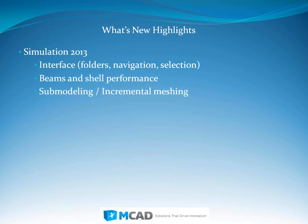What's been introduced, and what will probably be the subject of another webinar in the future for you guys, is submodeling, where we can do what's called incremental meshing. We can mesh individual parts now. We don't have to remesh the whole model if we want to change something about a particular part, about how it's capturing the geometry. We can also run these submodeling studies where we take a larger assembly and break it down into smaller parts and look in detail at some of the more refined areas where we can get extra refinement and dig into it a little bit further that way.